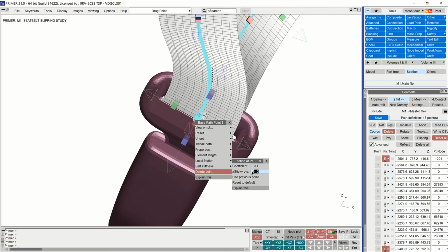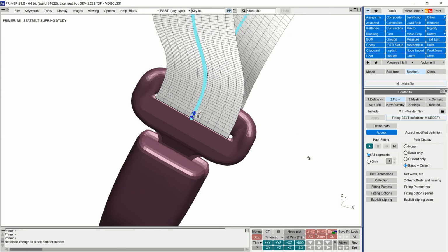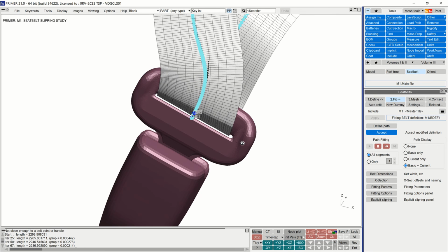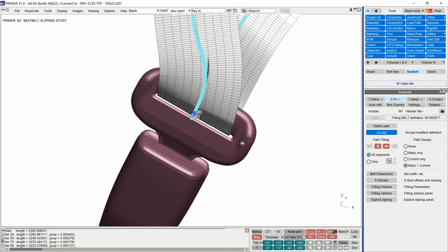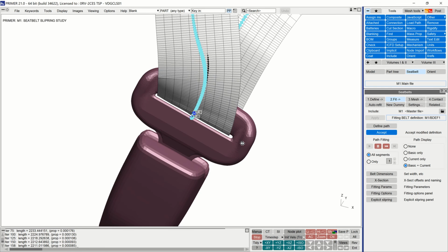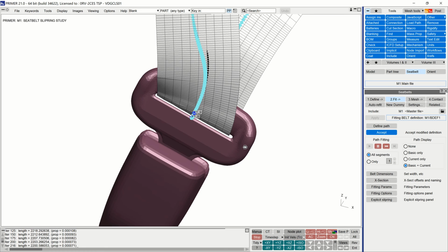Sticky points can be accessed through the basic path points options, and they define the number of central path points between 2 neighboring basic path points that will stick when they make contact with the structure. This only applies to the central path line, which allows the outer edges of the belt to fit correctly, while the central path stays close to the initial contact point.